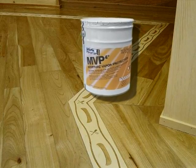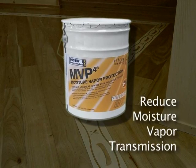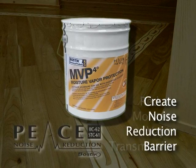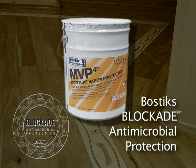Bostik's MVP4 has been formulated to reduce the rate of moisture vapor transmission originating from the subfloor, create a noise reduction barrier over the substrate, establish an anti-fracture membrane that can bridge cracks up to 1/8 of an inch, and MVP4 contains Bostik's Blockade antimicrobial protection to inhibit the growth of bacteria, mold, and mildew.